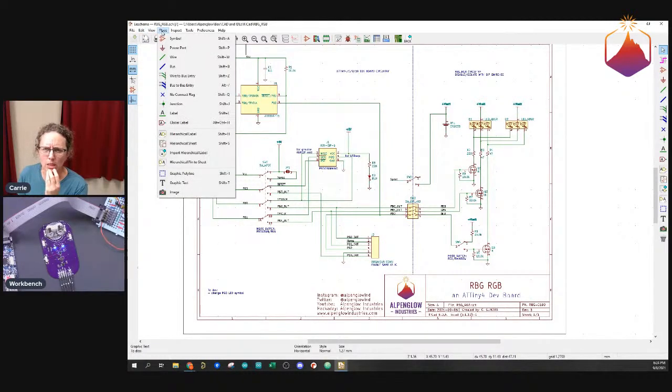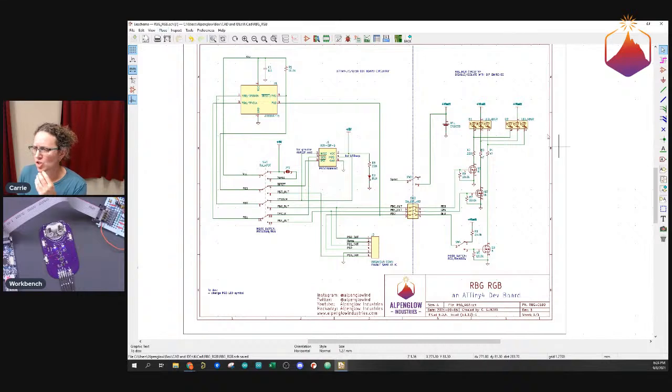What that would do is check if I have any wires that aren't connected to anything, that just end in the middle of nowhere. It would also check if I've set up rules about certain pins being inputs and outputs. I would make sure that an input was connected to an output and that 2 outputs weren't connected together, that kind of thing.